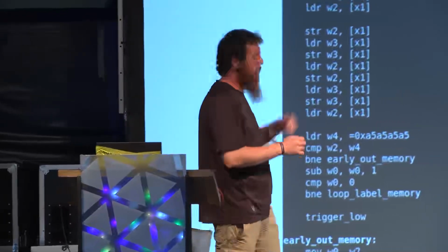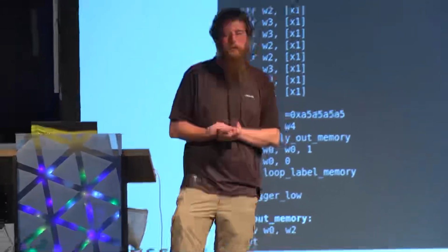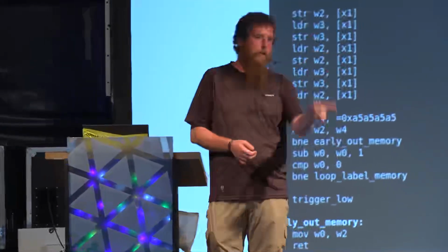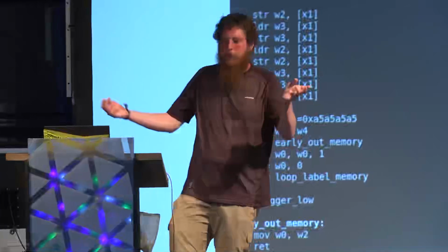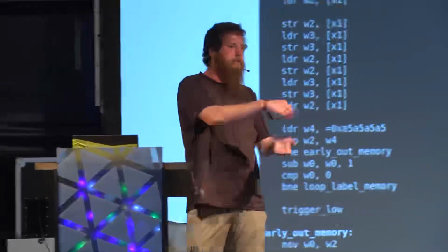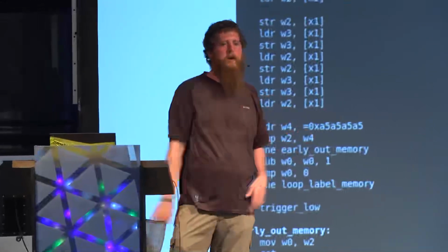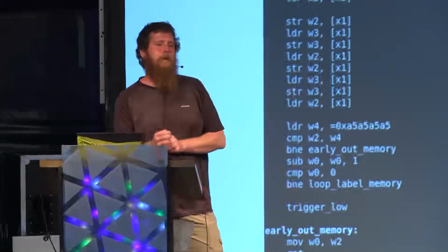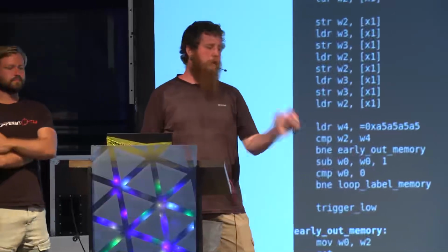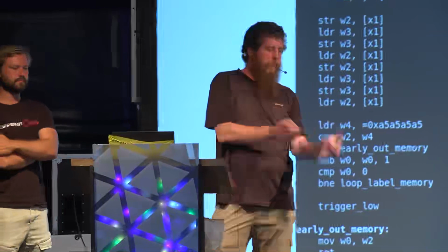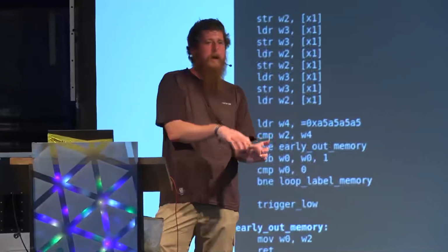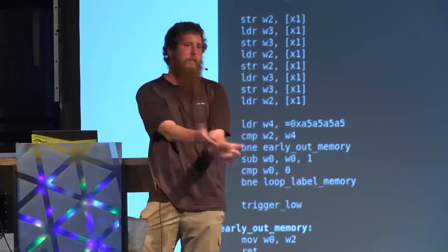In more complex targets and targets where we don't have control, we can use other signals to trigger on. So to say, from this point in time, wait. That can be reading from an eMMC. It can be some EM emanation from another component. It can be many different things. But that's the basic idea. We find some operation, something that's fixed in relation to what we want to glitch, and then we just wait a certain amount of time after that.